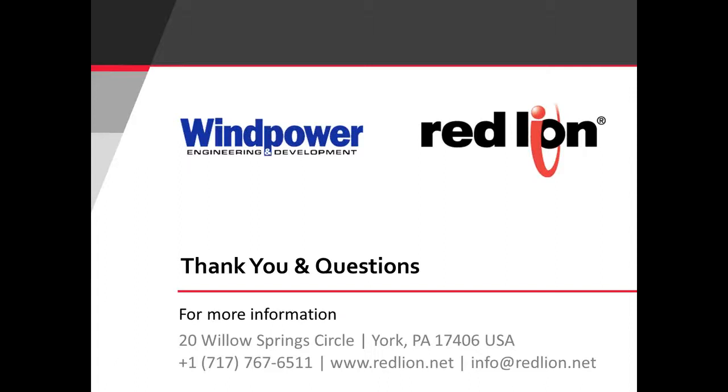So in the network, we look for redundancy for the power input, because it's a lot like our PCs at home. That's why industrial devices don't use fans like a computer, and we offer redundant power inputs, because the power source is typically the highest point of failure.